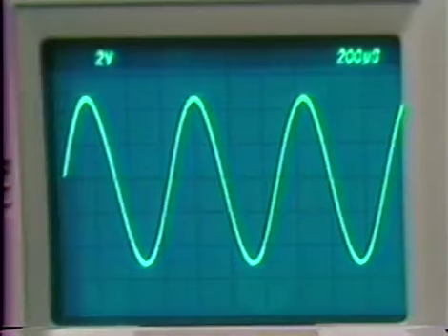The harmonic distortion in this one is 80 or more dB below the fundamental. So the idea of putting in a slow loop to control the amplitude does a very, very good job of giving us a spectrally pure output.